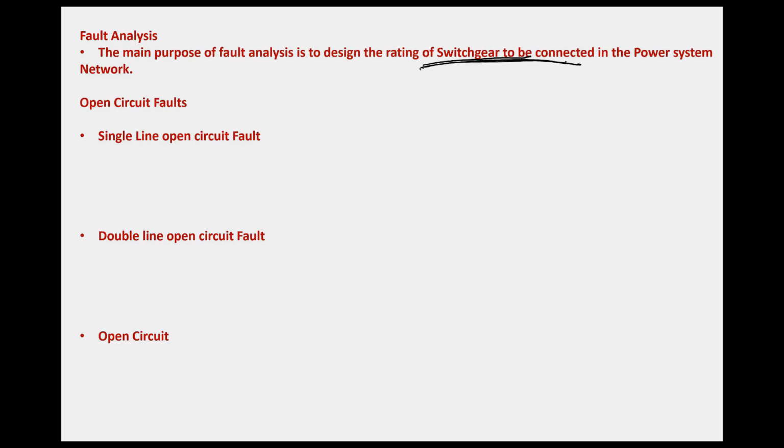So when you are putting the circuit breaker, that is the MCB, you have to ensure the breaking capacity of that circuit breaker. If you have an MCB in your house, just go and look. First, there will be one reading like C25, C10, C12, C32. That is the normal current rating. When I teach circuit breakers, I'll explain with figures. But below that, there will be a very small rating where they might have written 10,000 ampere or 6,000 ampere or 20,000 ampere like that. The small number that is mentioned below, that is called breaking capacity.